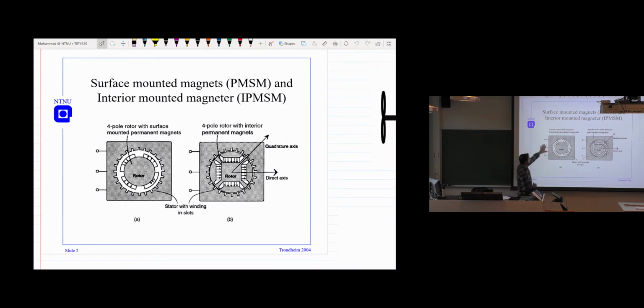What you see is we have the regular machine, and we have the coil there. We can put a concentrated coil, something like the three stator coils, concentrated. And then in the synchronous machine, we have the field winding, and we supply the field current from another source. So there are many different ways of supplying this field current to the synchronous machine.